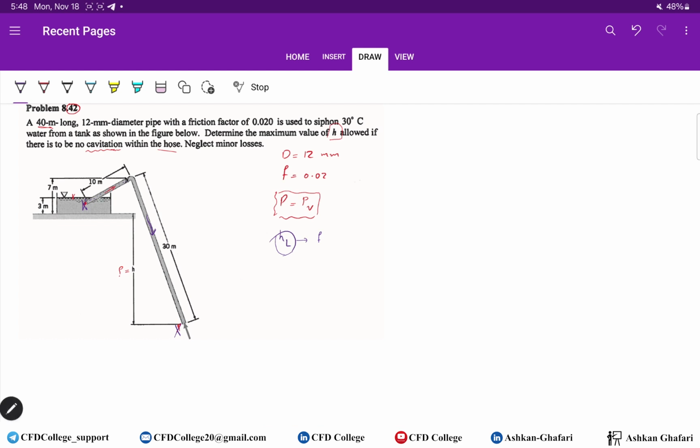So here, until this point, the pressure is decreasing by two factors, moving upward and head loss. But here in the second section, pressure will decrease a bit. I'm not telling that pressure is increasing. I mean, at least hydrostatic pressure will help us.